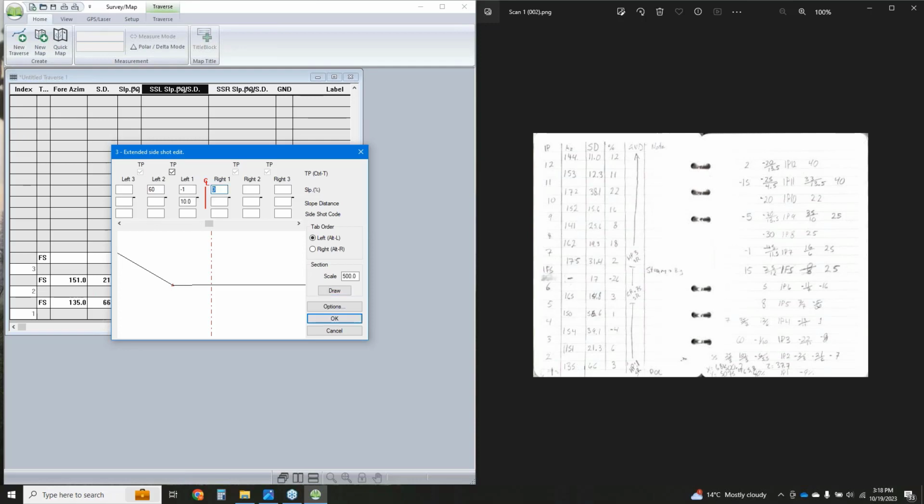On the right side, well, we want to go minus 22. I hit tab to jump to that other cell, and we want to go minus 22 for 11. So 11 meters, I'll do shift tab, and then we'll go minus 8 for the rest. Now we'll notice here I'm not adding an extra distance. So if I just leave that without defining the distance, it extends it on for, well, quite a ways. We can change that and we can see that it's going on for seemingly forever.